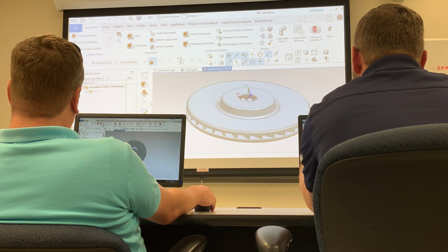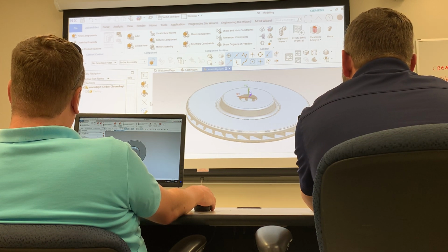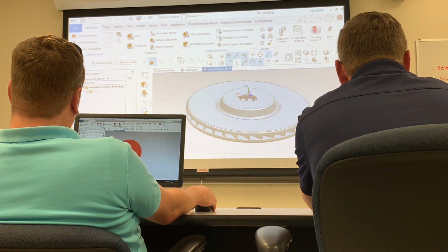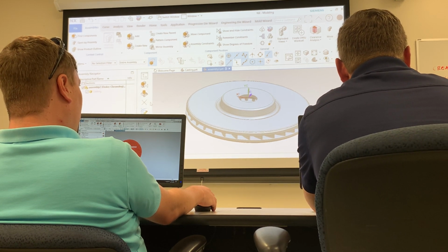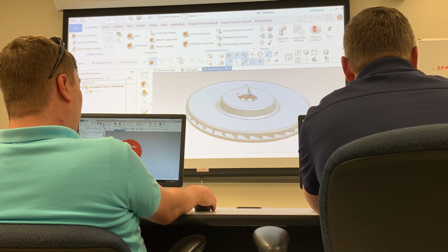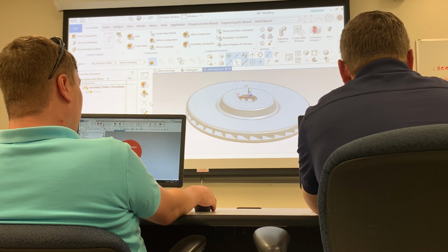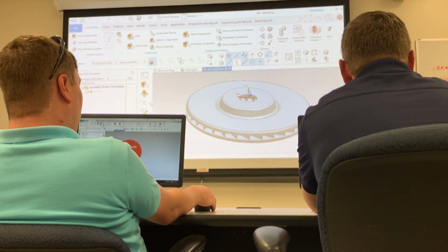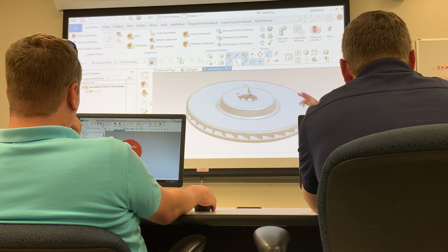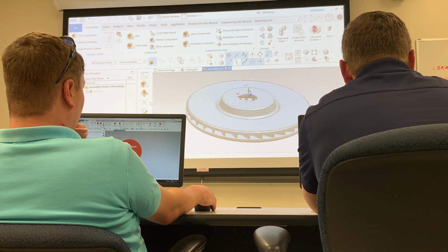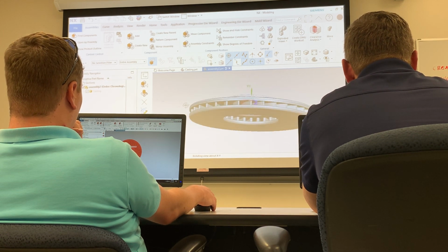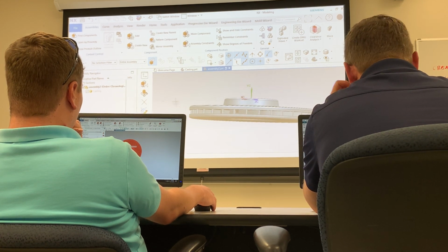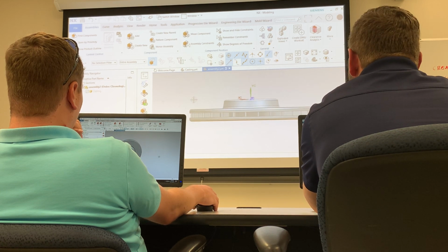The casting original wouldn't care. It just keeps going and doesn't know. In fact, we could take that one casting and make a whole bunch of different product lines out of it. We could machine it into different brake rotors, do different hole patterns. So we could have 5 or 6 or 20 different machined rotors that are all based on the same casting. And that's very regularly done.